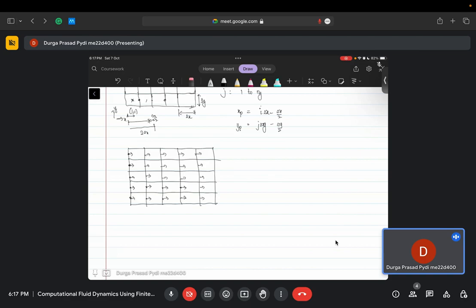This is essentially the one we are discussing. When you are using the Gauss-Seidel method, these are my unknowns, but instead I'll add one here and one here also, and use them as boundaries, and then I will not update A east or A west on the boundary. Now you also need to have velocities on these boundaries. This is my south boundary and north boundary.